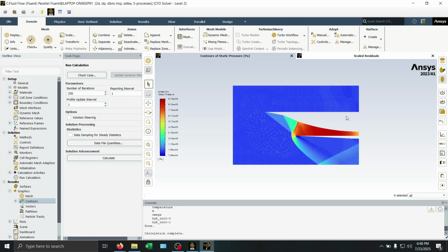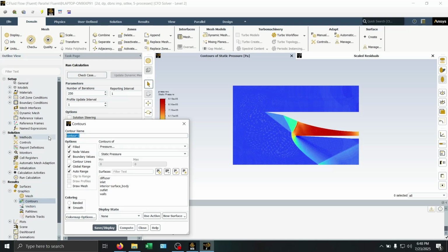Now it is slightly subcritical, right? The normal shock is not quite at the inlet, it's a little bit in front of it, but it is fairly close. So it's just a little bit subcritical, but not horrible. Then we'll do Mach.